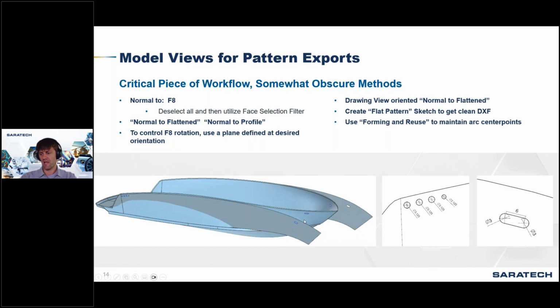So we put them in CAD, create a flat pattern, export that as a PDF and plot it on a roll format plotter, and we tape it up to the boat, and then we have our hole centers, so we can have accurate drill locations for production on the first article.